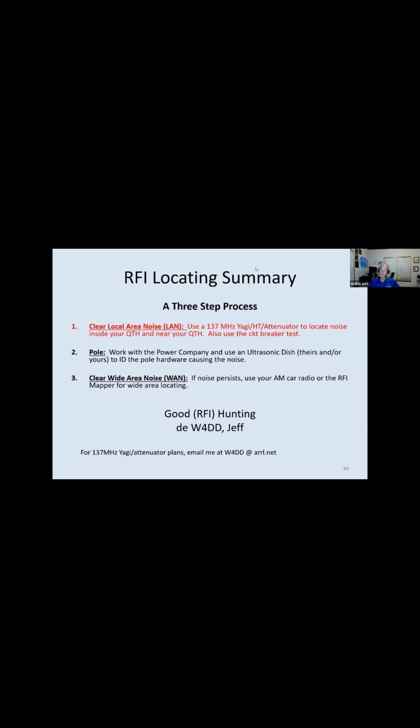I built this EME Yagi, 17 elements or so, 5 meters long. And the idea was to stick it out of my window and see if I could receive EME signals on the day when the EME contest was going on. Built the antenna, powered it up, connected up to WSJT on the laptop, immediately got a solid, nice, clean carrier at 432 megahertz, just what I expected. And then I realized, wait a minute, I hadn't quite pointed the antenna at the moon.